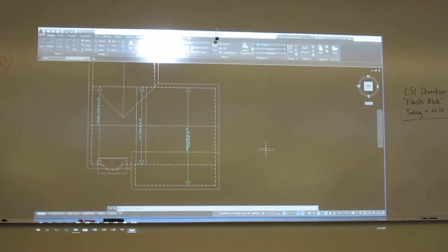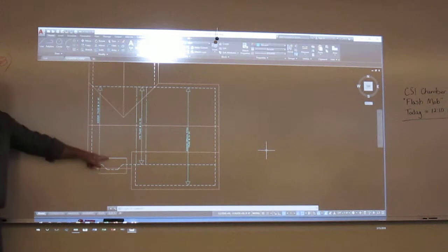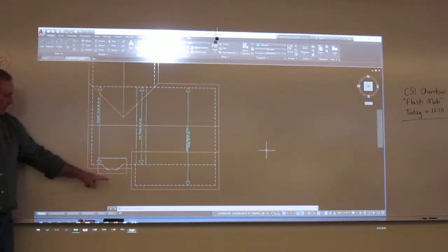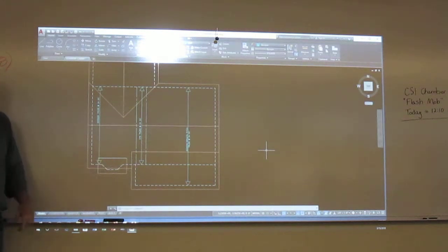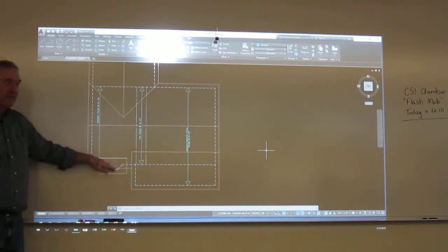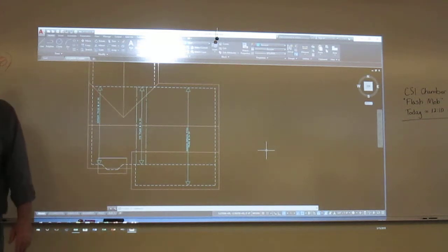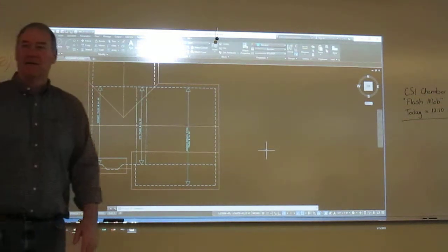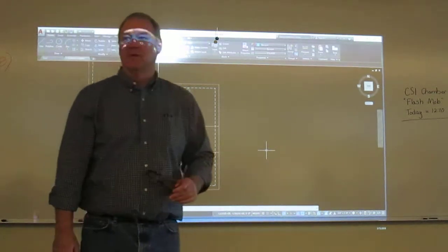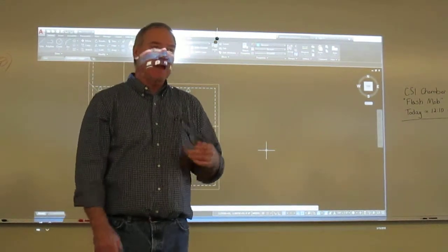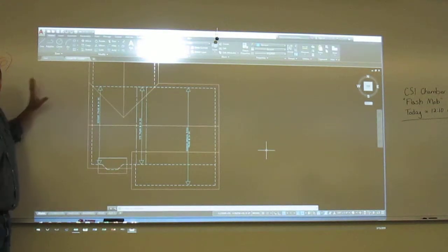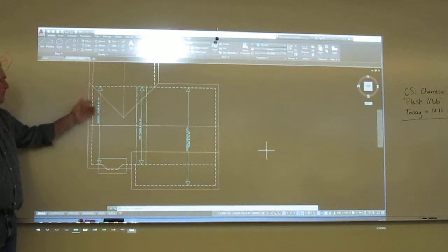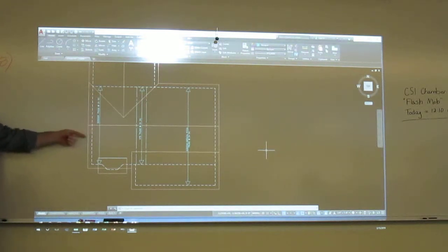Okay. Now let's handle this little guy. What happens when we get a little piece that we don't know what we're going to do? Okay. Now, can I find a truss that would do this one? Many times when you're doing these, you're going to use a mono truss. If you look at those shapes, see that little mono truss? That's a real popular truss over a porch. Now that happens really well on a gable end, like right here, because I got a big wall, right? And I can take a mono truss and just hang it right off this wall,